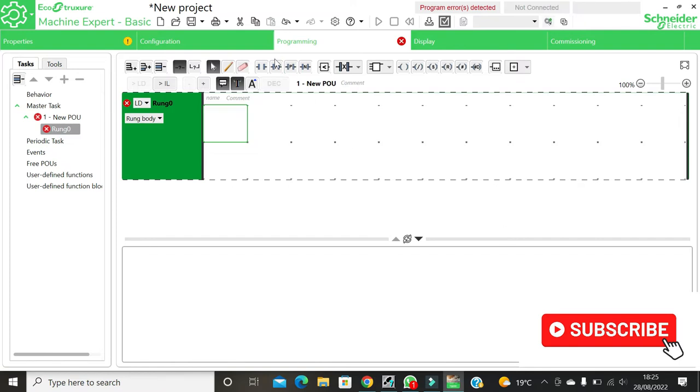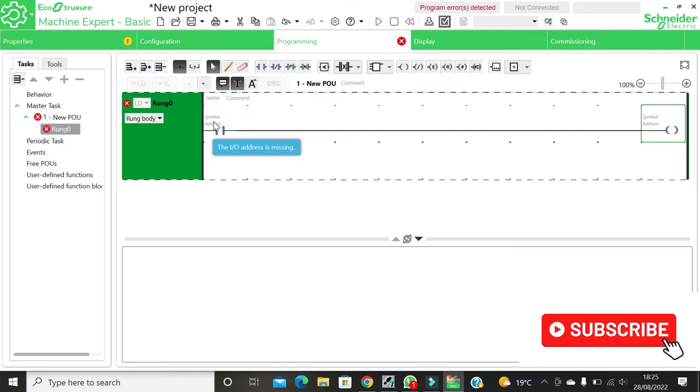I'll come here, I'll pick a normally open contact, then I drop it there. That will be our switch. And for a motor, I'll pick a coil and drop it there. So we have to assign addresses to both of them. So I'll start by the switch.